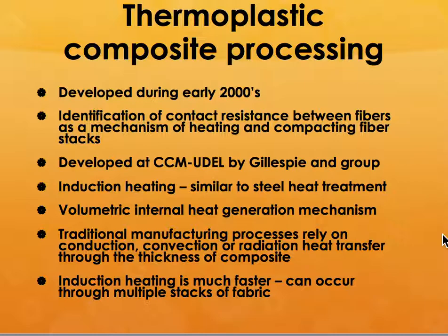So this was the process that I was telling you about based on induction heating. This was developed by the Army and the Center for Composite Materials at University of Delaware by Jack Gillespie and his group. Basically what you're doing is applying pressure, and at the same time you're applying temperature through induction heating. Induction heating is much faster, and it can occur through multiple stacks of fabric.